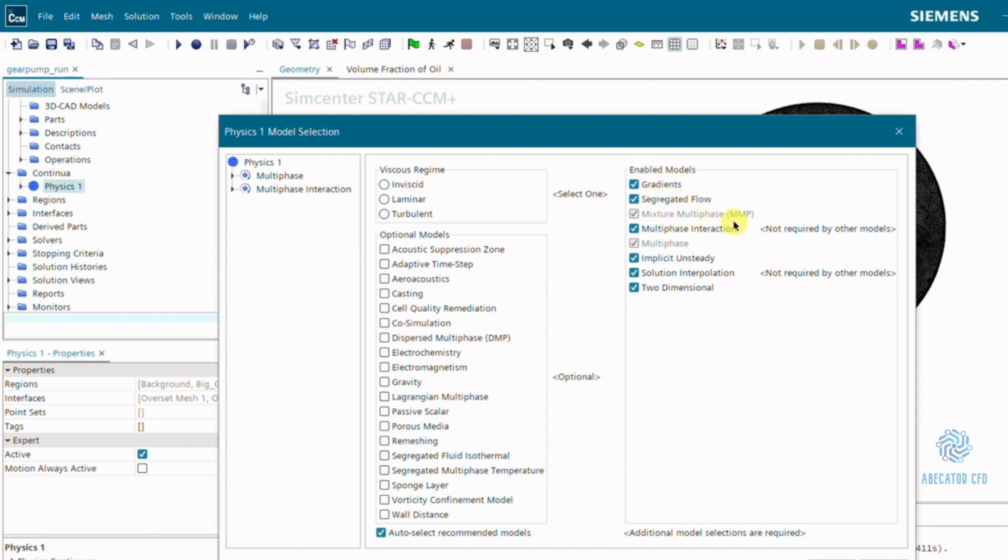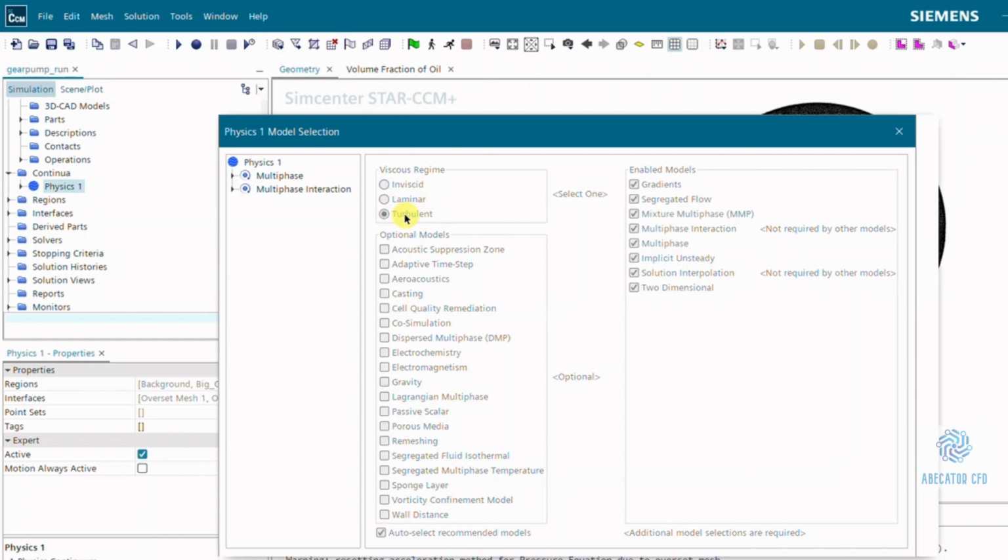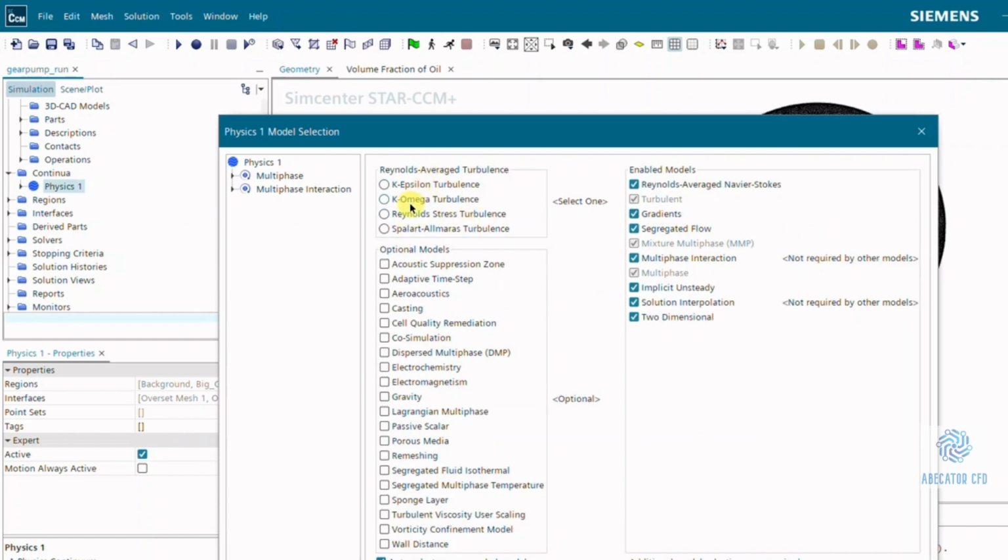For turbulence modeling, that is, to account for the turbulent viscosity, I have three main options. I do want to model turbulence, so I enable the turbulence model. Because this is a 2D example, STAR-CCM Plus automatically selects Thin/2D style options, and I choose the K-epsilon model.